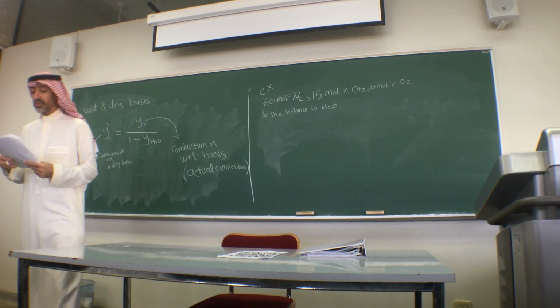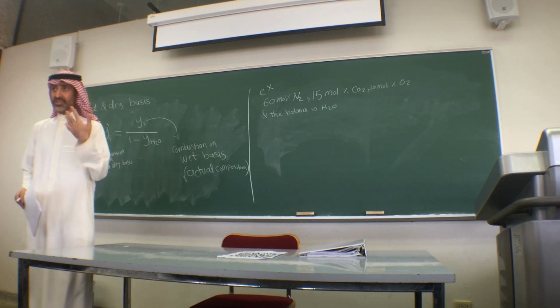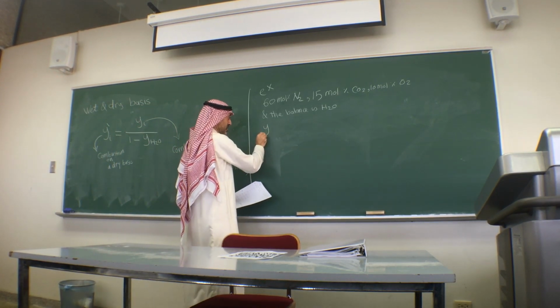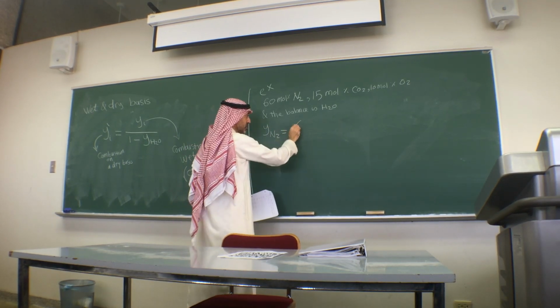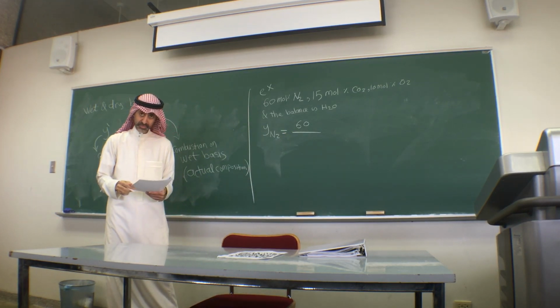Calculate the molar composition of this gas on a dry basis. On a dry basis, Y N2 prime will equal 60 divided by what?